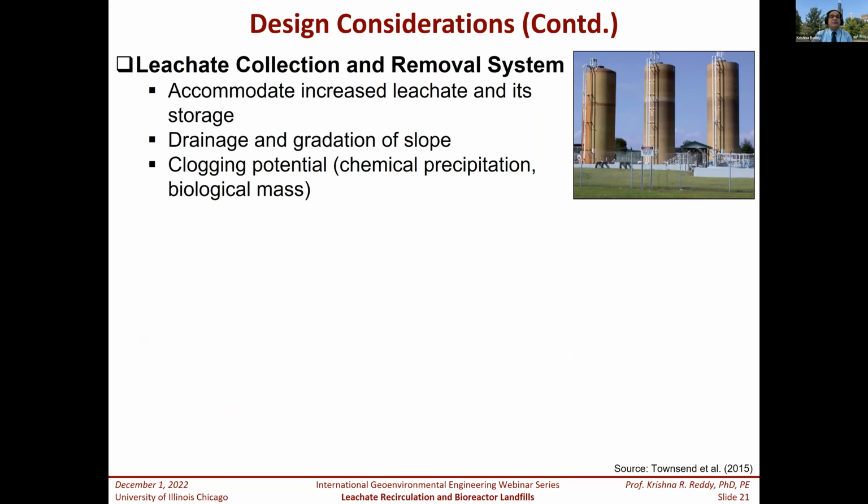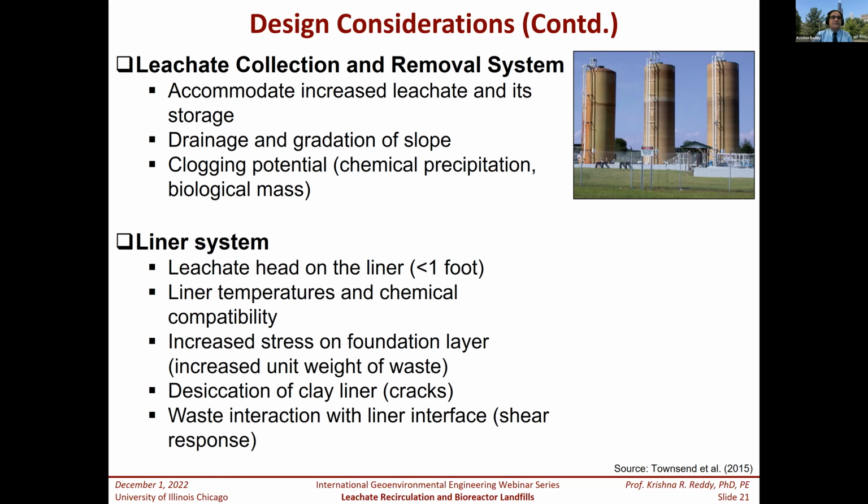And the leachate collection and removal system. You need to make sure you have a way to handle the leachate. If I have a landfill with excess leachate, should I store it on site? In some cases you don't have that much leachate generated, so you don't have any storage issues. And make sure that your leachate collection system works very well, because if you have clogging issues, you will not be able to collect it, and then the recirculation system becomes inefficient.